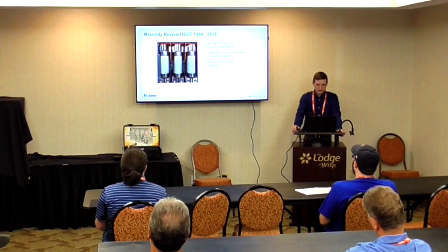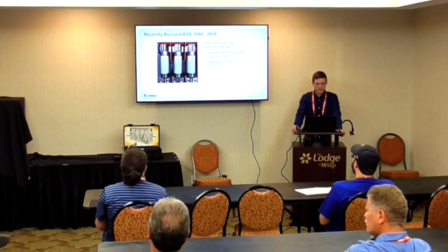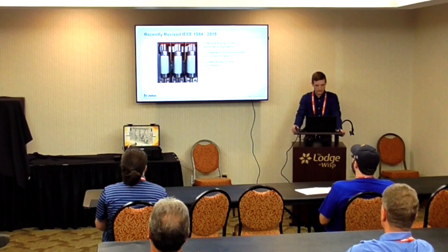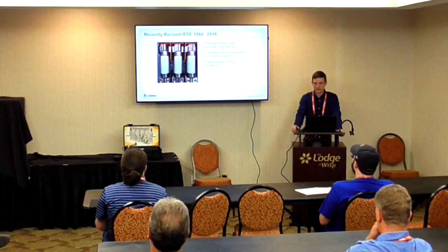Speaking of the electrodes, there are different electrode configurations now in IEEE 1584. We're going to cover some of those in just a second, but just keep in mind that the incident energy in some of these is 3 times what it would be in some others, and I'll show you the reason for that.